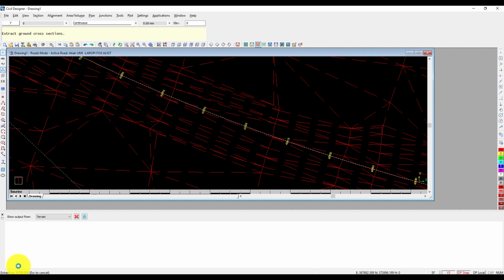As you can see, it's extracting along the chainage. Now we're on chainage, we are now maybe 20 kilometers in. Okay, so it's extracting everything, and it's going to look at all the different facets, and it's going to add a road template. Of course, with the magical power editing, I'll show you once this is done. I'm not going to take you through all this. So now we're on chainage 67, and it's extracting all the ground cross sections, and it's going to apply the road template. Okay.